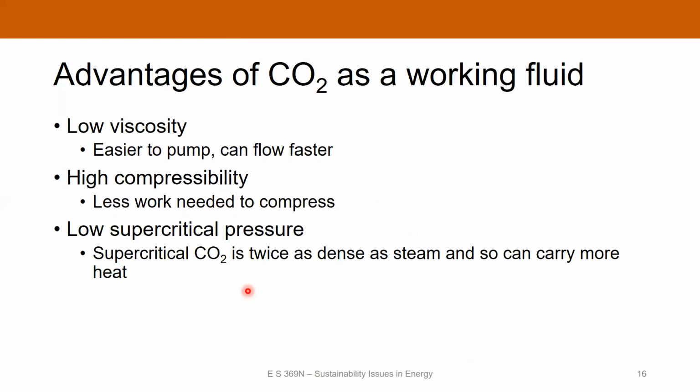Now, why is CO2 advantageous as a working fluid? Well, it has a low viscosity compared to a lot of other fluids. This means that it's easier to pump. It can flow faster, and you're not going to have as much energy loss from friction when it's flowing. It's got a high compressibility. So when you go through the compression cycle, you need to apply less work to it to compress it and heat it up. And it's got a relatively low supercritical pressure, which means that you can actually operate a heat pump with CO2 as a working fluid in the supercritical phase.